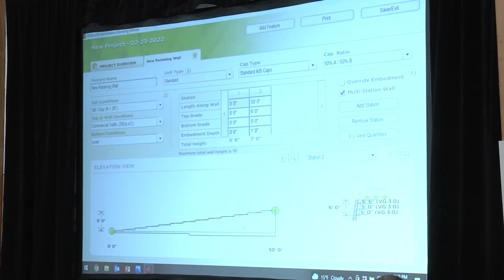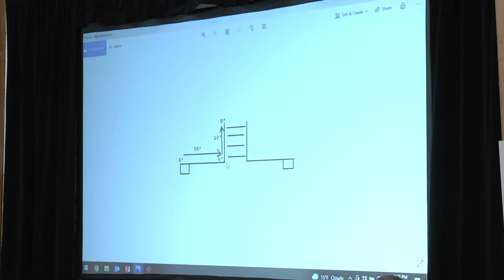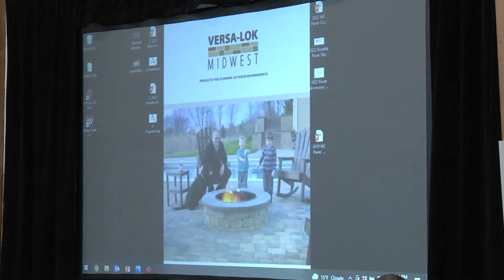Next thing, we said we were going to put stairs on our little estimate here. So I'm at the corner at 50 feet, and now we're going to put stairs in there, right? Well, if we're 6 feet tall at this going, and our rise to run is 6 inches by 12 inches deep, I've got to add 12 more lineal feet for this cheek wall. So I'm just going to add it into this one wall, right?